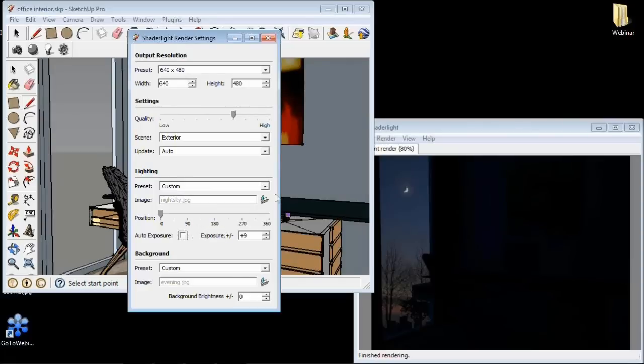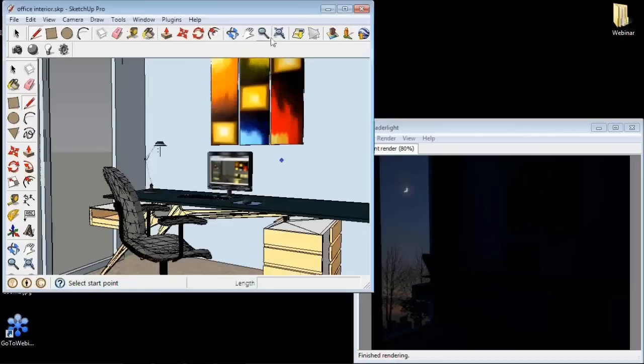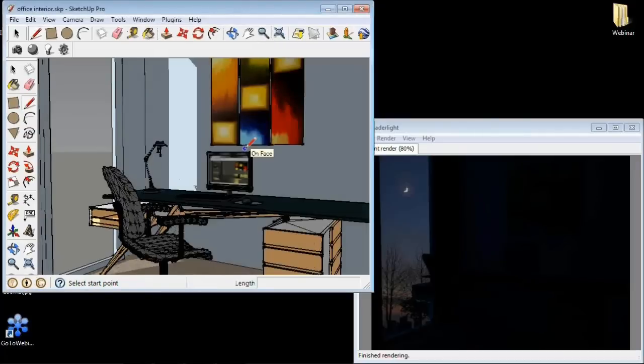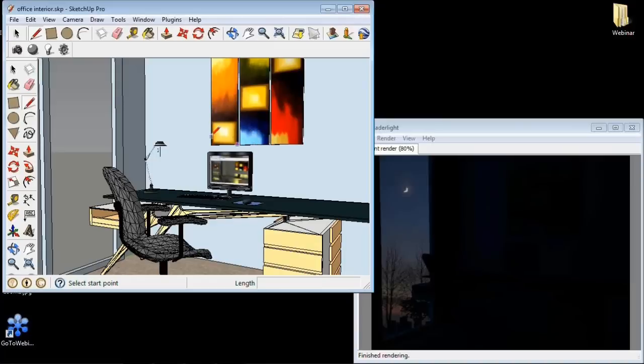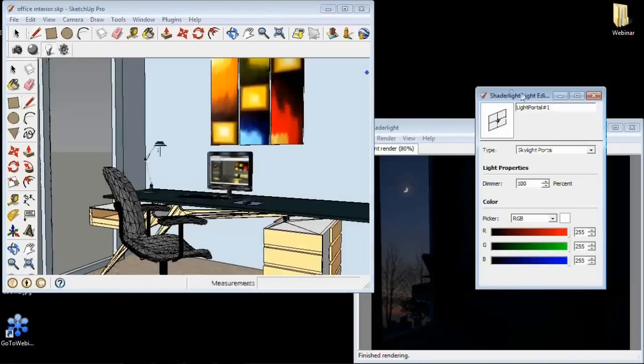But also, if you want to create a dark room and then put lights in the room, like we're going to at the moment, you might want to turn auto exposure off. If you put a small light into a room, the auto exposure will immediately try and brighten it up to be like a daytime environment. Now we can look at this as we start to put lights in the room.